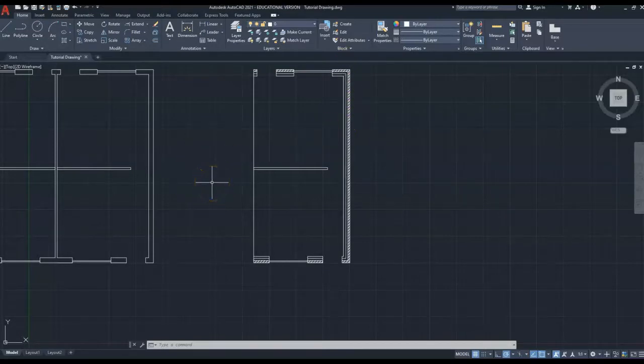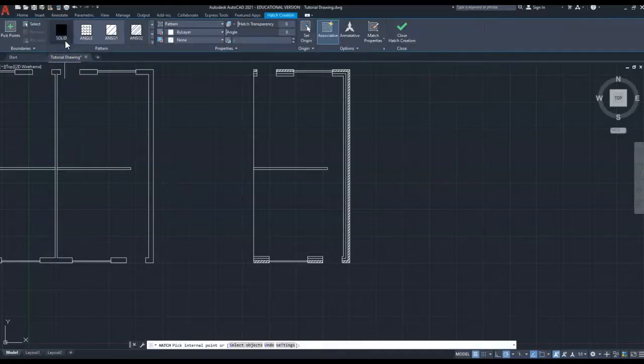So now I want to do the same for the internal blockwork. So I'm going to click on the hatching key again. That'll bring up the new command function. I'm going to click the block hatch, and I'm going to click pick points again, and then left click. I'm doing the internal skins.